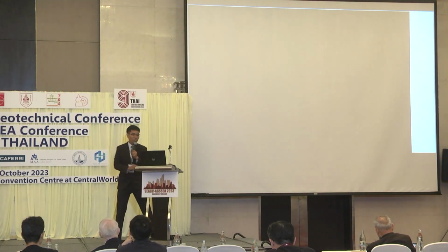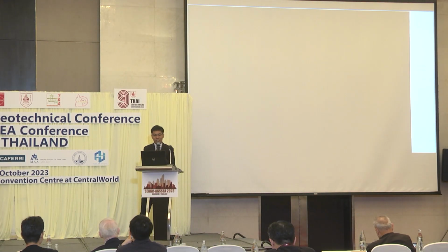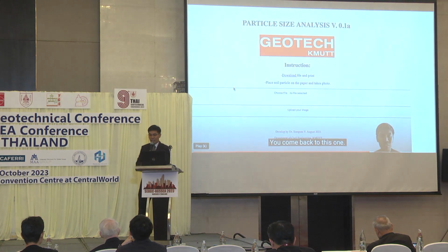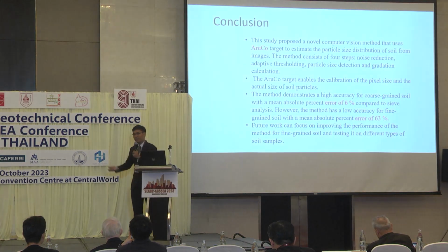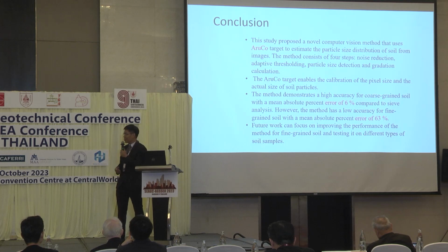And if you see it, it's not only the gradation. I also perform soil classification altogether. You can see that the soil is SW, SP, or dual symbol, and so on. You can see what kind of soil we have in the field.